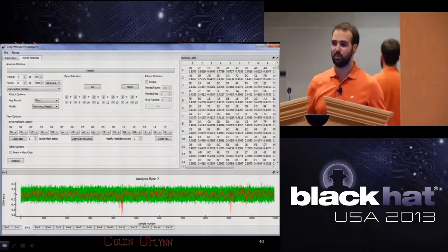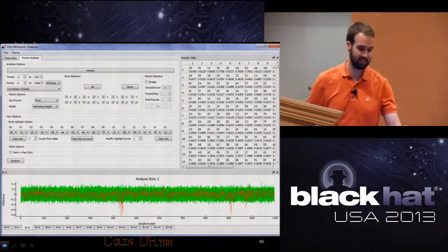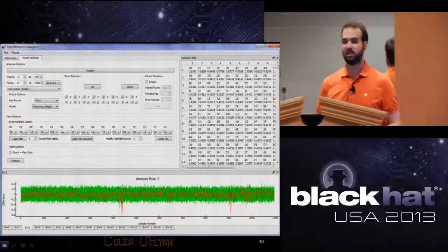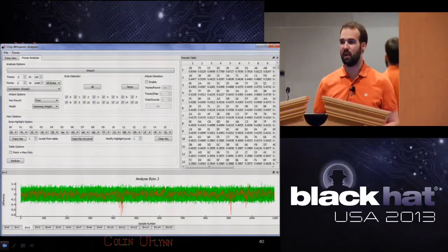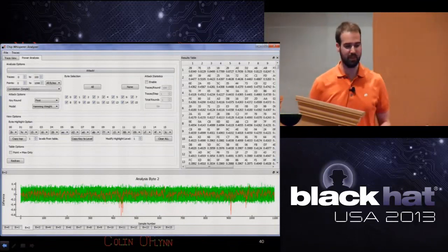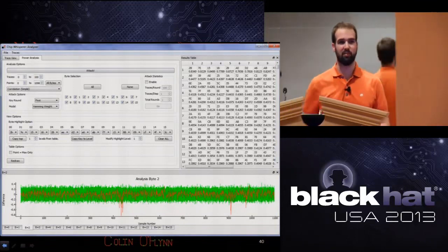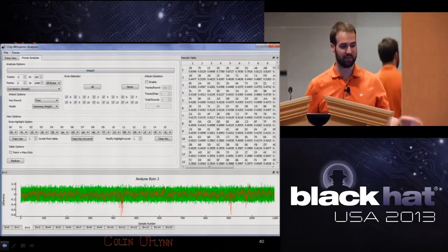So the theoretical limit of the clock speed: the ADC in this is spec'd to 105 megasamples. You can run it faster. You could overclock it; I've done 150 megasamples. You can play some games with undersampling that actually work okay. So I don't know how fast of hardware you can go. It depends a lot on what it is.